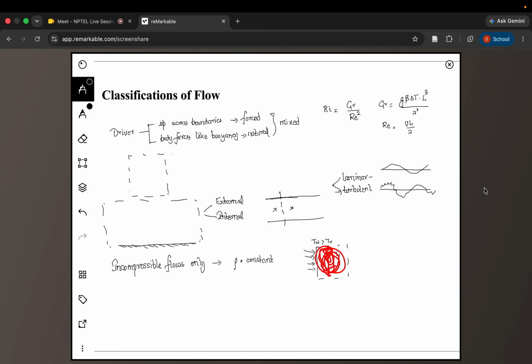The air which gets hotter will rise upwards, and the cooler air that is coming because of your air conditioning system will move down because it has a higher density than the warmer air. It flows down, and the hotter air moves upwards. So clearly, density is not constant here. So, can I use the incompressible flow assumption in this particular case?